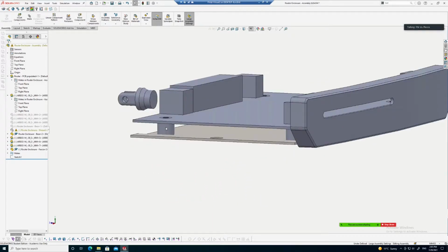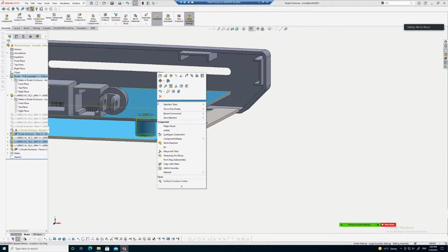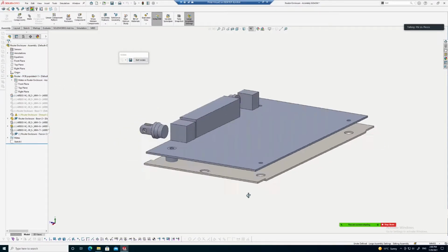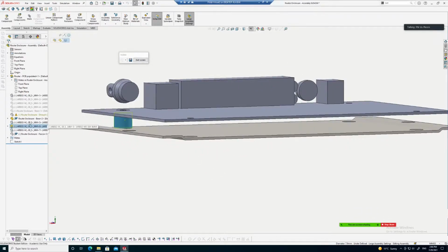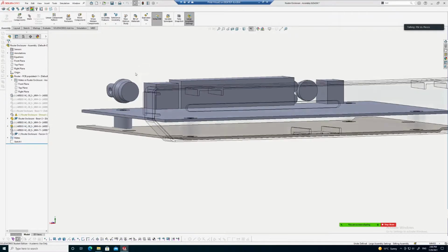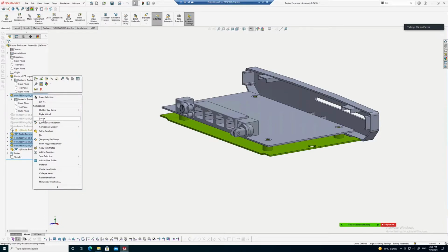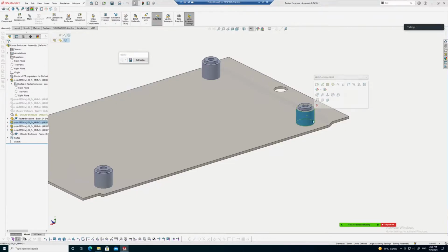And then for any two parts, let's say I wanted to find out about the mates between those three parts there. Once I've got them selected, I can right click and isolate just those three parts, which makes it much easier now to access the parts that I want. Or I could just have two. You can see I'm actually missing some of these others. So let's exit isolate. Let's just Windows select those ones, right click and isolate. So now I've got just the parts that I want. Let's say I wanted to play with the mates between that part and that part.